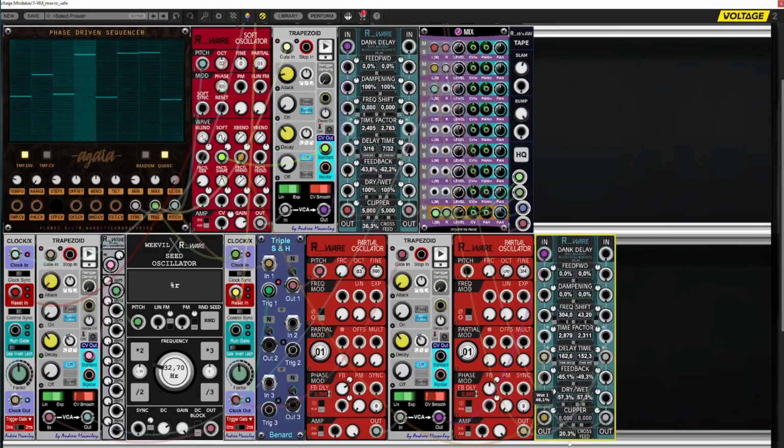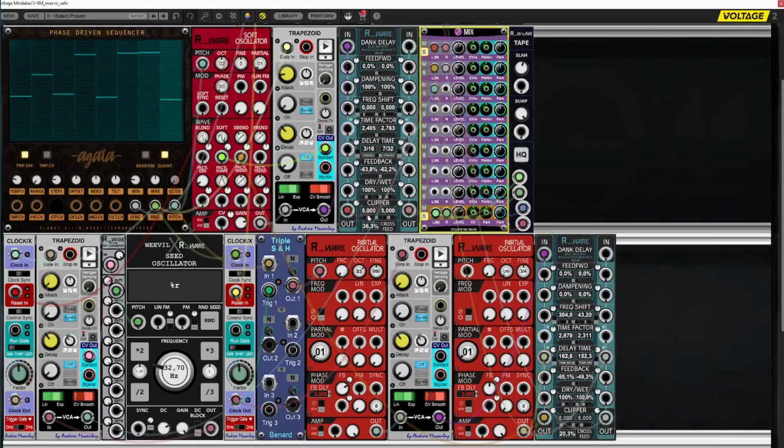Finally, at the output, a special anti-alias clipper with soft and hard clipping options keeps your signal within a set limit. This can add some nice character to your delay signal and prevent it from getting too overwhelming in a mix, especially with high feedback, feed forward and/or crossfeed. You can disable the clipper entirely by setting the switch all the way to the left.